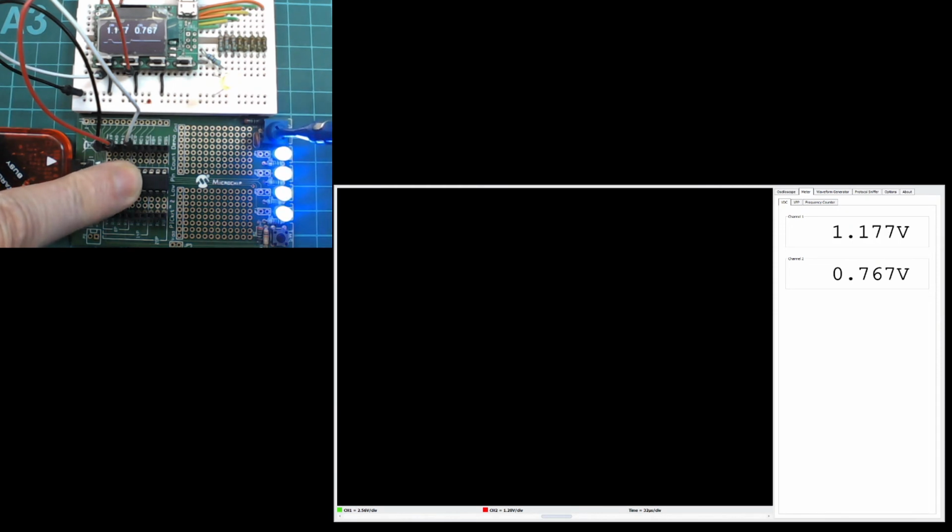So as I rotate the potentiometer, the voltage increases. And so does the bottom number there of 3.8, the maximum voltage that's on my channel 2, and that's because on this board there is a current limiting resistor that's effectively creating a voltage divider, which says the maximum is 3.82, and that's okay. And as you can see, as I rotate it, the voltage drops.